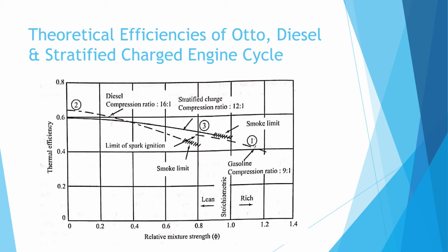In SI engine, higher hydrocarbons in exhaust are due to the flame quenching at the combustion chamber wall. If charge stratification is used, this quenching effect is drastically reduced. It is because almost pure air will be present near the cold combustion chamber wall at part load.